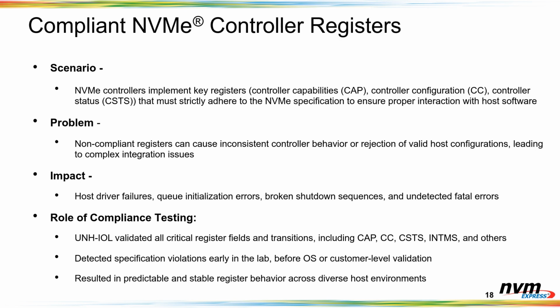Moving on to the next one. So this is, as Feng had told, about the key registers, the main registers: the capabilities, the configuration, and the controller status registers. They must strictly adhere to the NVMe spec. If the registers are not compliant, then we might have very inconsistent controller behavior, or rejecting valid host configurations.